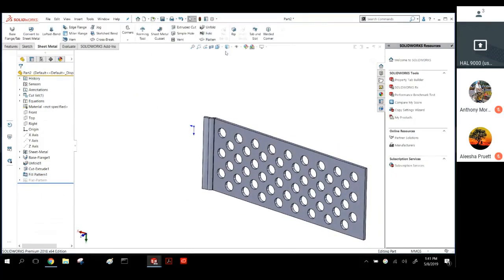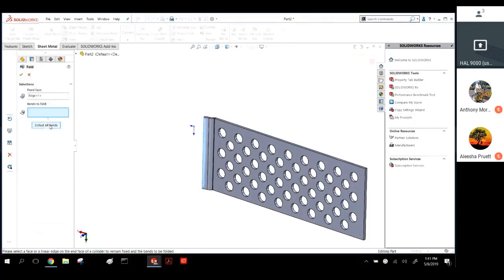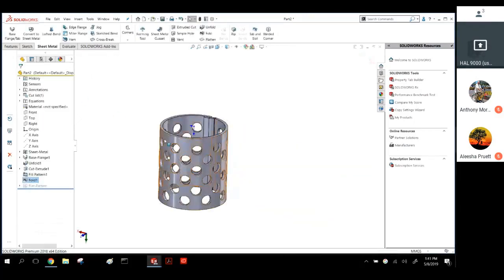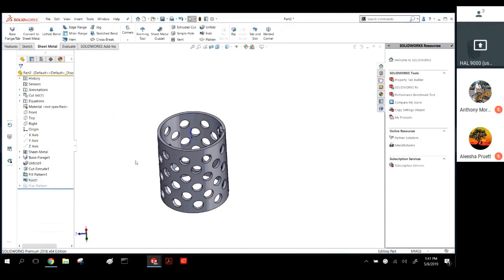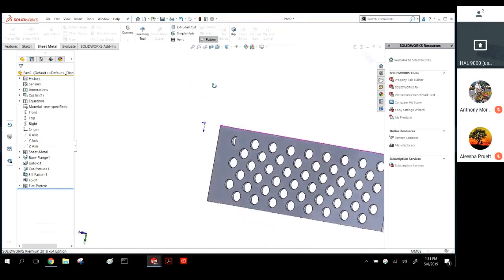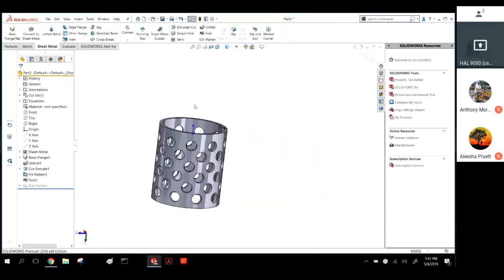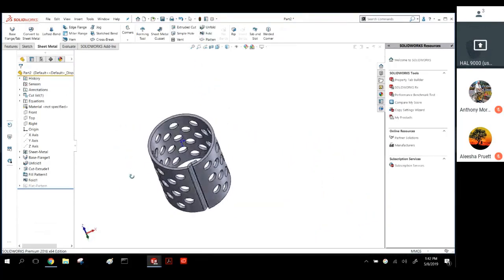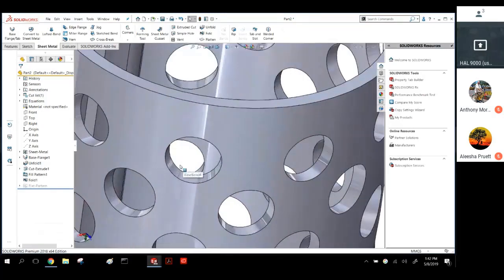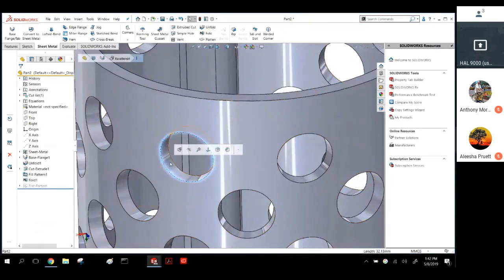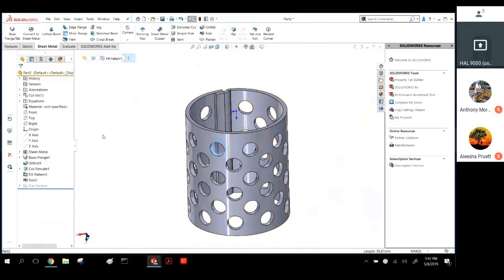Just like I did before, I'll go into my sheet metal, choose fold, select the bend that I did. And now it's taken that they're perfect holes when it's flat. So it's sort of the opposite of what I did with that normal cut. They're perfect holes when I do my flat pattern. And then those holes get deformed or stretched. You know, it's wider here than it is here because that K factor is actually stretching those holes around that sheet metal bend.